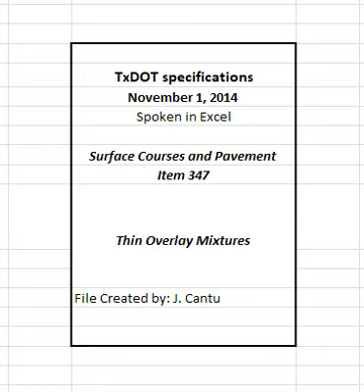4.4.2.1.8 Trial batch production. Provide a plant-produced trial batch upon receiving conditional approval of JMF1 and authorization to produce a trial batch, including the WMA additive or process, if applicable, for verification testing of JMF1 and development of JMF2. Produce a trial batch mixture that meets the requirements in Table 8. The engineer may accept test results from recent production of the same mixture instead of a new trial batch. Obtain and provide approximately 50 pounds of trial batch mixture in a sealed container, box, or bags labeled with the CSJ number, mixture type, and date for the overlay test.